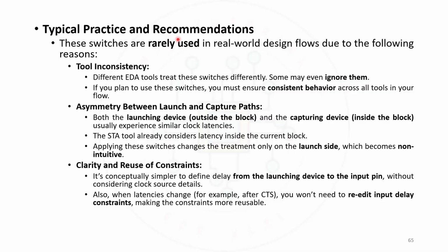So coming to the practical and recommended approach, these switches are rarely used. Generally, in real-time scenarios, we won't be using these particular switches called hyphen source latency included and hyphen network latency included. So these switches are rarely used in the real world design flow due to the following reasons. Tool inconsistency. Different EDA tools treat these switches differently. Some may even ignore them. If you plan to use these switches, you must ensure consistent behavior across all tools in your flow.